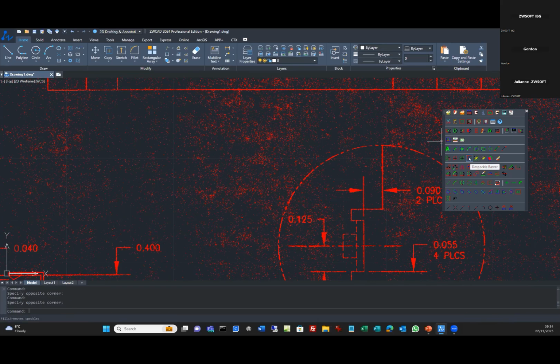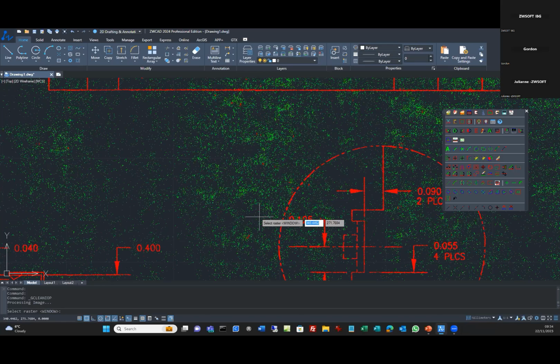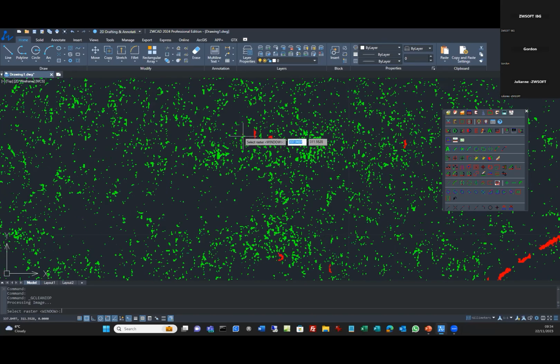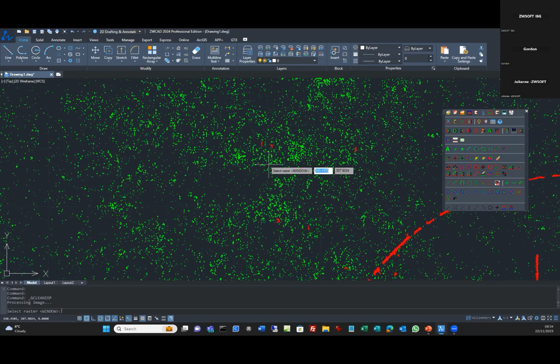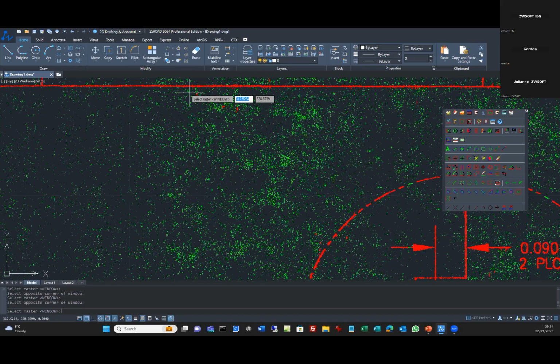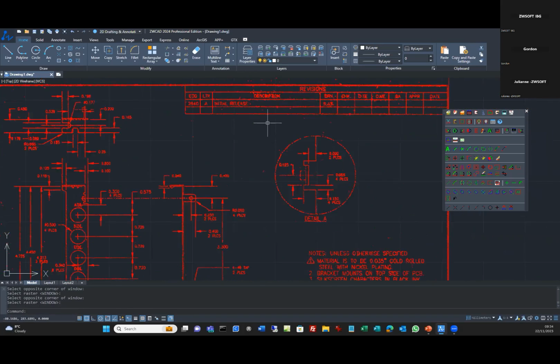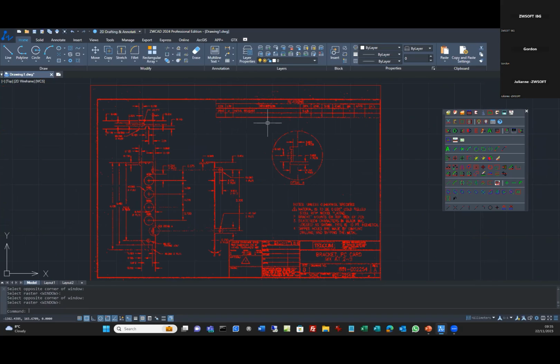So we have various methods to do this. We can either despeckle, where you choose a speckle size and apply it to the drawing, or we have a cleanup command that will either show you what it's going to erase, or we can just automatically get rid of the data. If I use this one here, everything that goes green is going to be removed from the drawing. You can see that there's still some large data that's still red. That could be like a decimal point, could be some sort of quote or something within the drawing. So it looks at speckle sizes and thinks, okay, well, that could be data. We can actually still add, because we're in the selection method, so I can keep adding items to the selection. Everything that's green is going to be removed from the drawing. Hit return, and there you have a nice clean drawing that you can actually read and start working with.